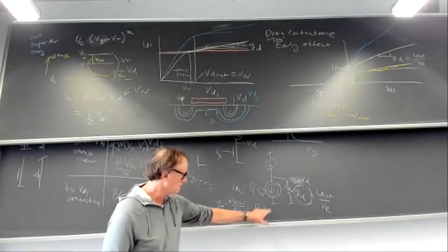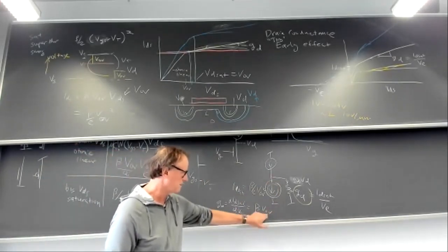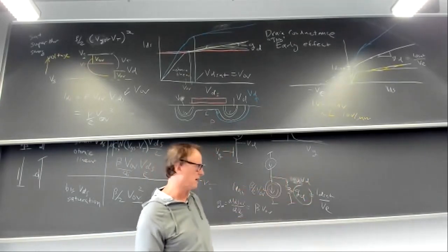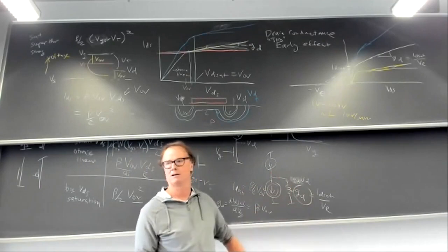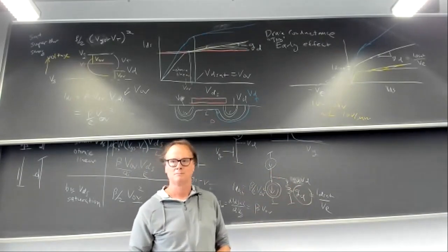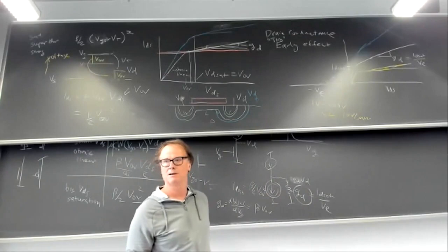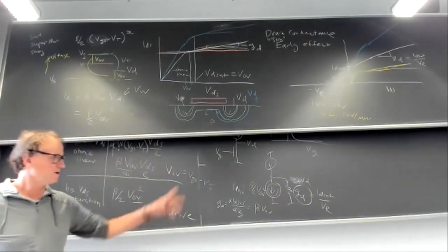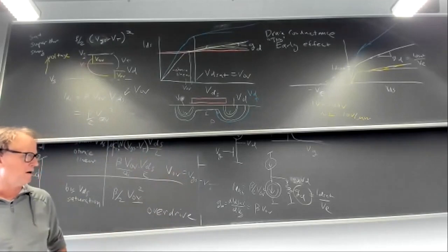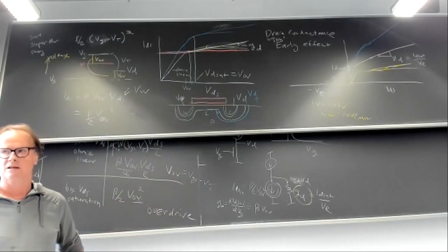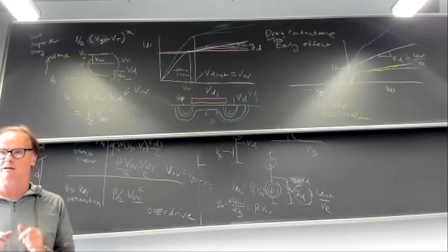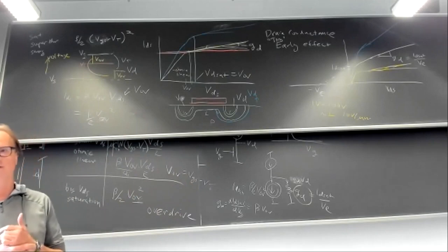Now, if you express this in terms of current, this has the gate voltage and this has the drain voltage, but you can now work out what the voltage gain is exactly of this circuit in literally one line. I'll leave that for you guys to play with. You'll see it in the lecture also, recorded. But then you can find out that above threshold, given a reasonable Early voltage and beta and stuff like that, it's easy to get a voltage gain of like 100. Putting in reasonable values, you can easily get a voltage gain 100 amplifier out of one transistor.